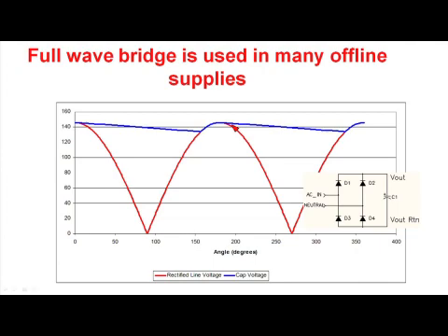For instance, if you had a smaller capacitor in your circuit, it would discharge more, and you would end up having to operate with a lower input voltage. A larger cap reduces the range that your power supply has to operate over. And that's important because that sets the turns ratio in the transformer, and it sets many of the circuit stresses. The higher that the input voltage needs to be for the power supply to operate, the more efficient the power supply is.